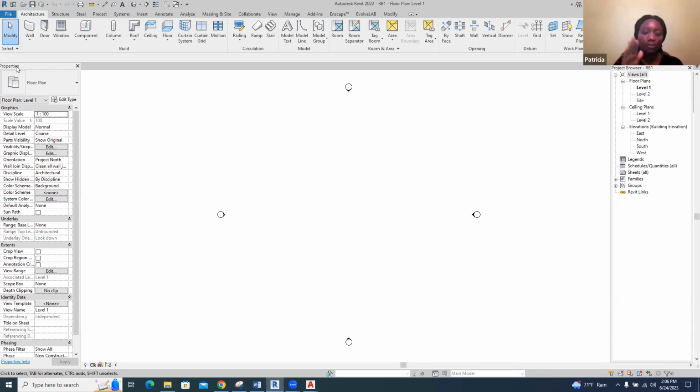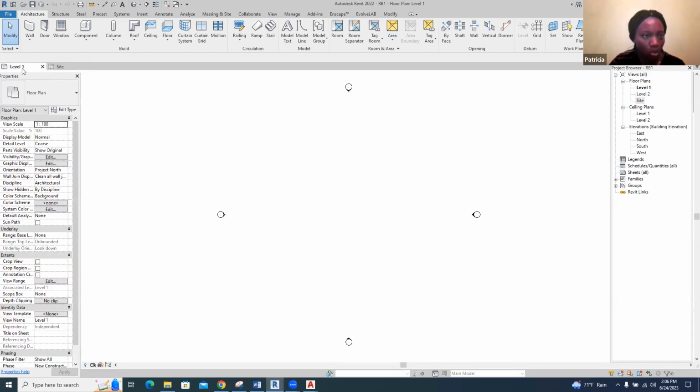If we want to do the project, let me say we start from the site up. So if I come to my project browser and double click on site, it takes me to a new level called site. So here we had level 1, and then we have site. For everything you click in the project browser, you would see a new window. So now we are in the site level.